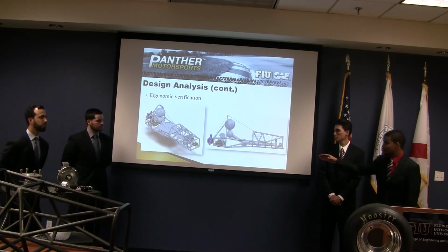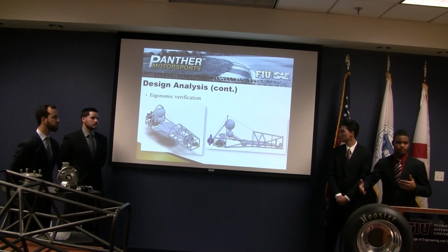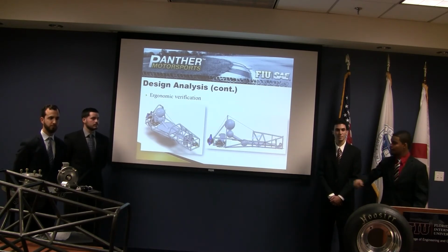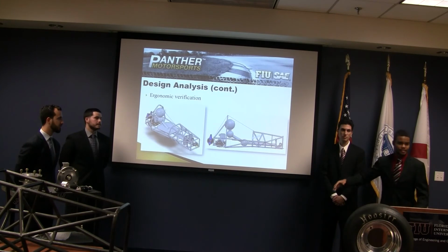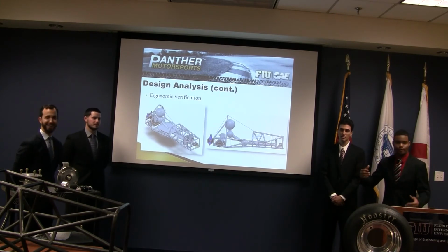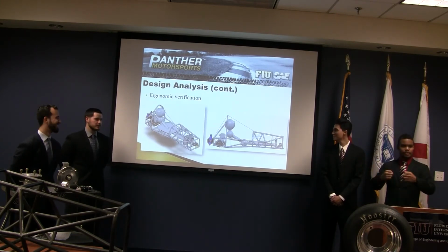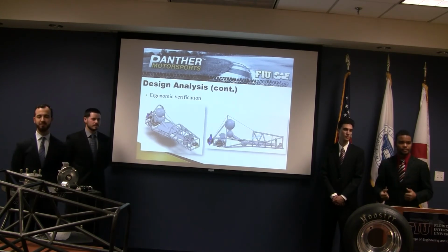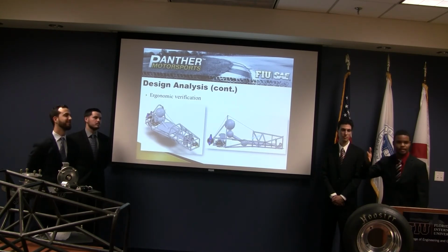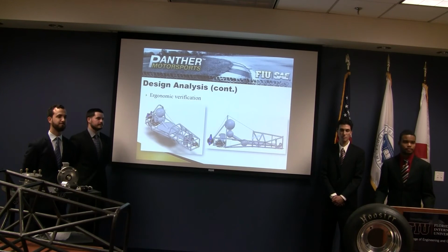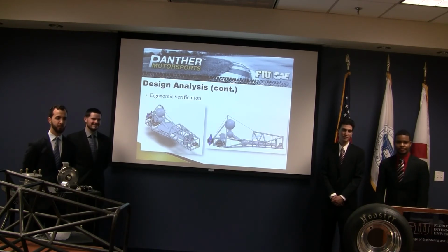Also to note that the driver's seat position and the pedals are adjustable, so we can adjust it in order to fit the driver. This 95th percentile is a guy who's like 6 foot tall, which is none of us. So when we actually have the pedals and the seating, we can recline the driver in a more comfortable position. This is just to make sure that the template they use in competition actually fits within the rules. That's my last question, sorry guys.